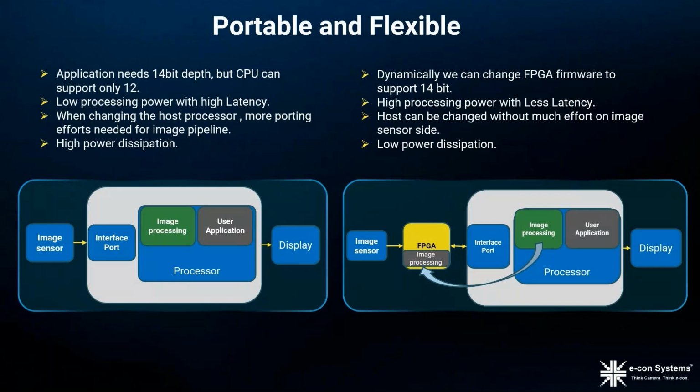In an embedded vision product, the ISP is the basic block needed to get quality images. It can be implemented in two different ways. As shown in the block diagram, the one on the left uses an inbuilt ISP from the processor. The other one, on the right, has an FPGA ISP outside the processor.